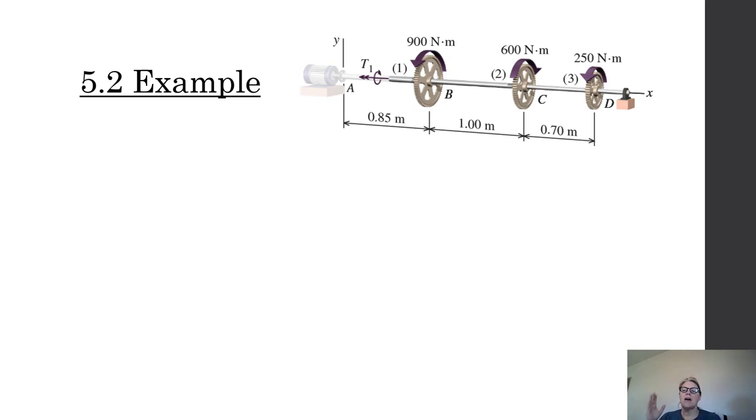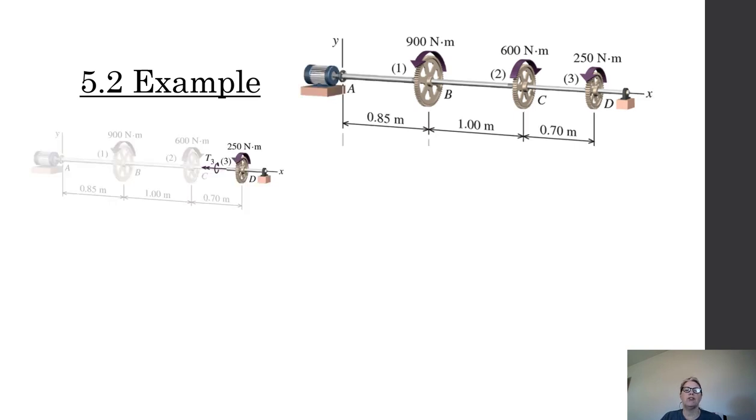Okay, if I have a shaft that has several gears and pulleys on it, and I need to design this shaft or find the internal torque, the internal stress, or the angle of twist, I have to first draw a torque diagram. And so I'm going to start over here at the right.